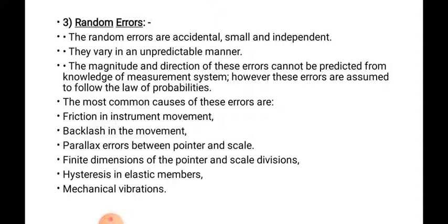Then we will observe that the pointer of the measuring device exactly overlaps the marking of the calibrated scale. But suppose we observe the scale or the pointer of the instrument from somewhat offset. In that case it may appear to be intersecting with another marking from the measured one. That is nothing but the parallax. Are you getting it?